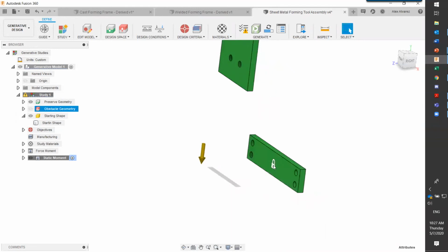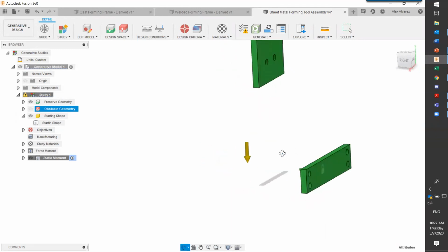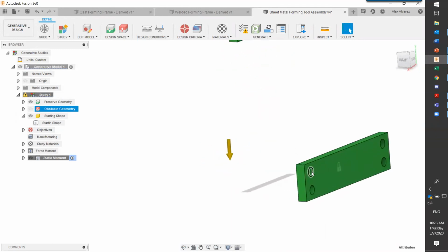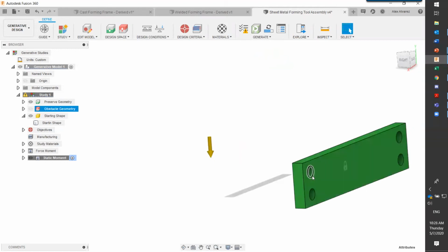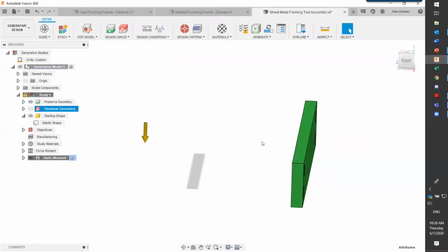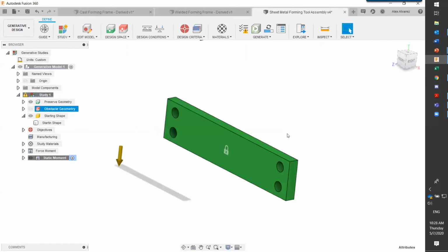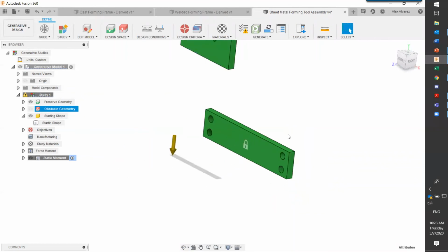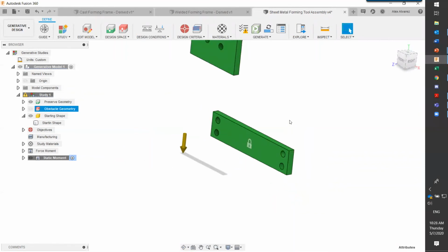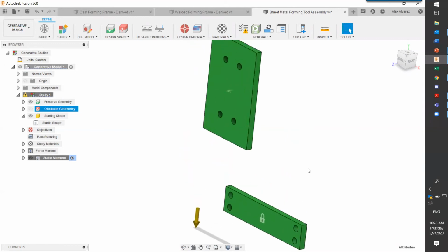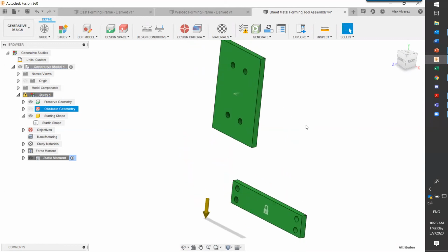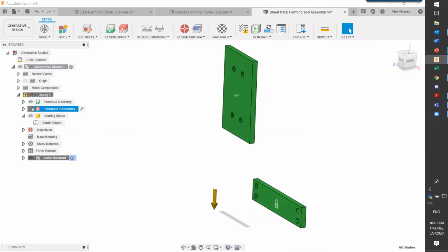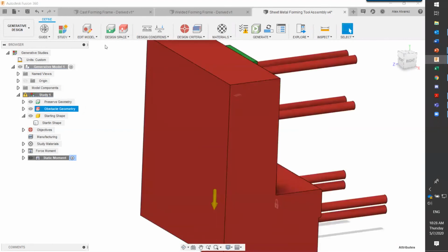We could have done this a little bit more realistic. We could have fixed the bolt holes here, right? And then maybe had the head of the bolt here, so have a cylindrical surface that was fixed as well, so that it actually shows like it was a bolted part or a bolted assembly. I wanted to keep this simple just to make sure that we were able to run the simulation on time. But those were your conditions, and that's the next step after you do some of the prep work for your model.